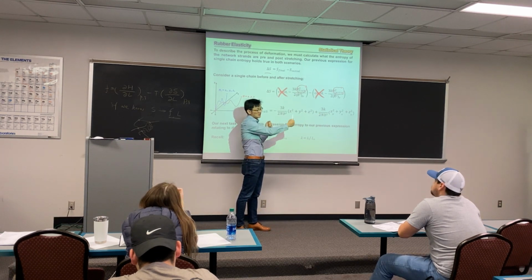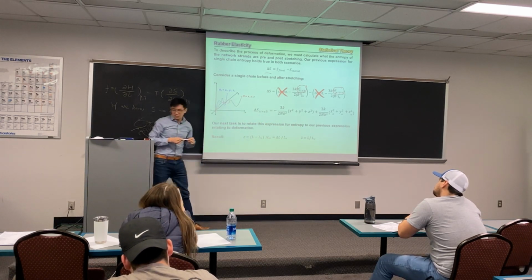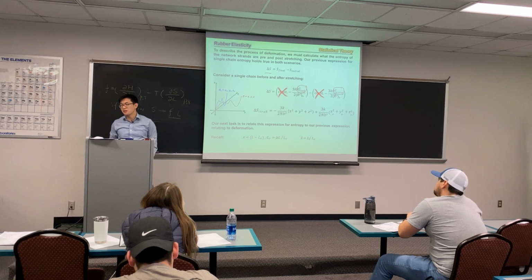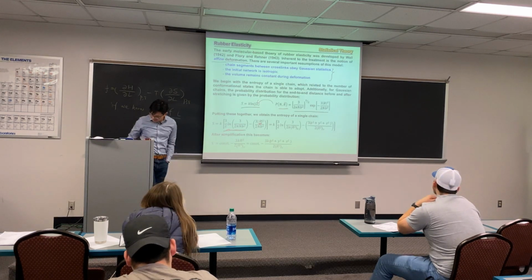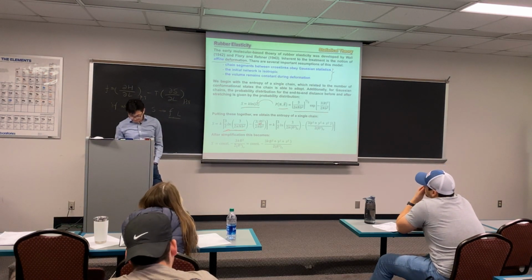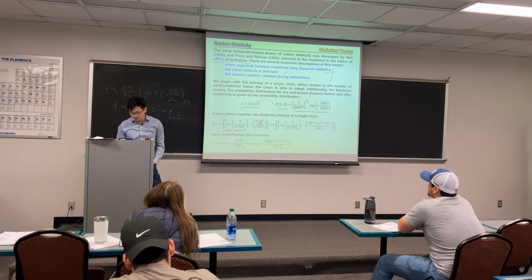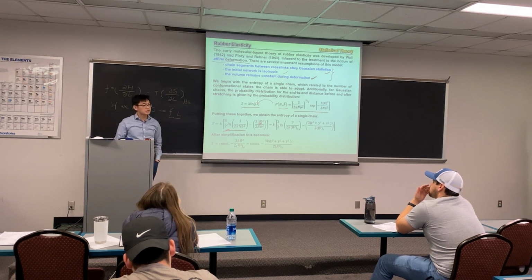Stretch your polymer twice, your network will deform macroscopically to twice the length. Any guess, thoughts? Brave idea? We have another assumption, right? Let's go back. We use this assumption to get to the entropy. Basically, we use a Gaussian chain distribution to calculate S. Isotropic is also part of the reason we can get there. How about this? Can we use any useful information from this? There's no volume change during deformation.